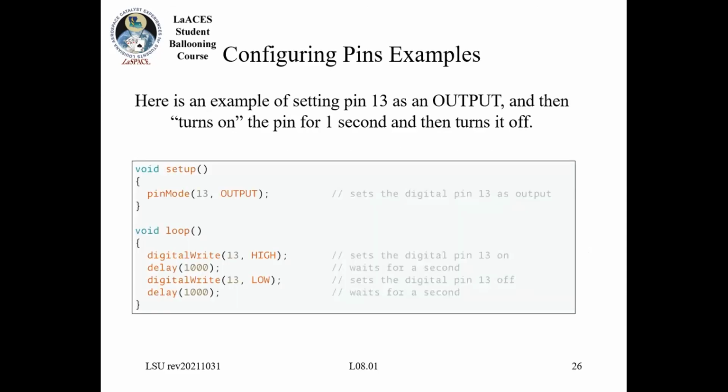And here's an example, right? Oh, and in fact, I misspoke, because obviously pin mode can have the value of input or output. So here, this line in the setup, we are calling pin mode. We are setting the mode of pin 13. So that's why pin 13 is the first argument. And this is actually a constant that's predefined. So that's why it's all caps. So it's just all caps OUTPUT.